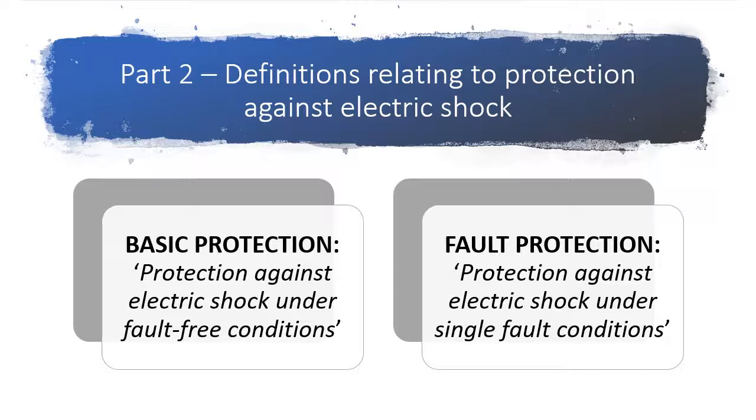Our two main definitions that we've already come across, basic protection and fault protection, are here as well. Protection against electric shock under fault-free conditions and protection against electric shock under single fault conditions. Basic protection and fault protection feature very heavily throughout the entire standard.